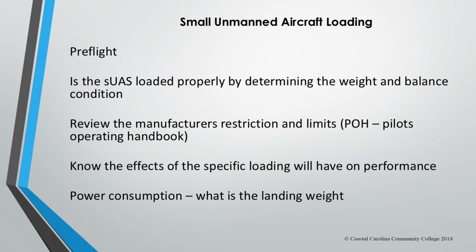So before we start, is the drone loaded properly by determining the weight and balance condition? Review the manufacturer's restrictions and limits in the pilot's operating handbook. Know the effects of specific loading on performance, and how much the loading is going to affect your power consumption and how much it is going to weigh when you go to land.